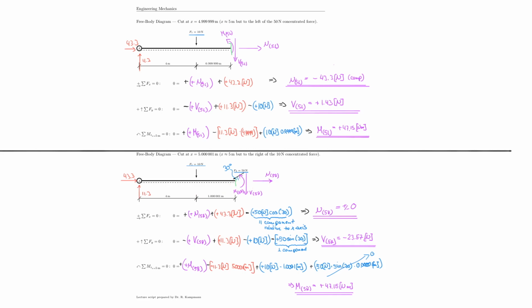I could have created the system here where I cut the same part, but I now introduce only the force here, which is, I believe, 23.57, and then I cut right here where I will bring in now my internal forces, my shear force, my normal force, and my moment.